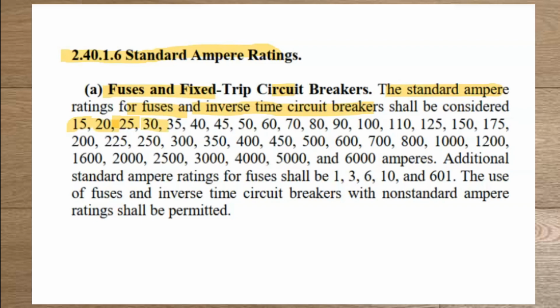What we got earlier is 24 amperes, so the closest is 25, but I don't know if you have or can quickly find a rating for that. Commonly, the next is 30 amperes, which is available in our market. So I prefer to use this 30 ampere inverse time circuit breaker.